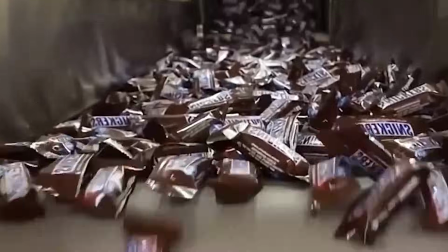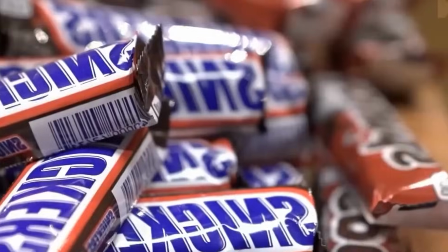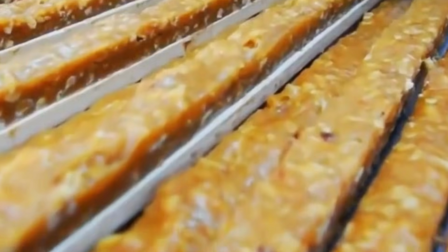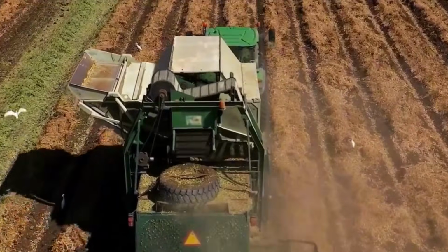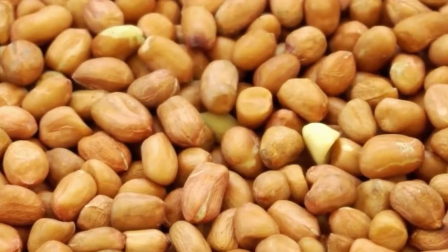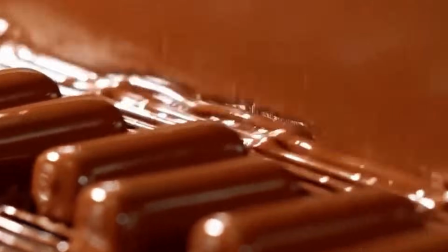Viscosity and temperature of the peanut butter are constantly monitored by inline viscometers and thermocouples, with feedback loops adjusting jacket temperature and pump speed. A caramel layer is prepared by cooking sugar, glucose syrup, milk solids, and fats to a target temperature of 115 to 118 degrees, followed by emulsification in a vacuum mixer to remove air bubbles. The caramel is applied as a third layer over the peanut butter using a heated roller spreader system with a calibrated gap to ensure uniform layer thickness.